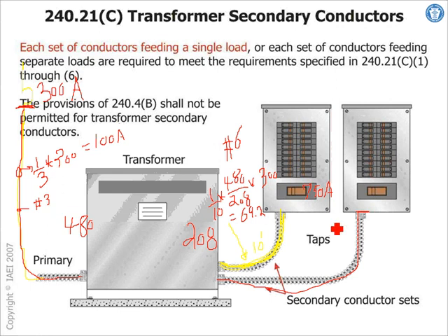Now on this side, look at the minimum again. On this side, same thing, you take a third, but now we are going to the secondary side, so you have to multiply by the voltage, which is 480 divided by 208, multiplied by 300. So you have to adjust it to the voltage.